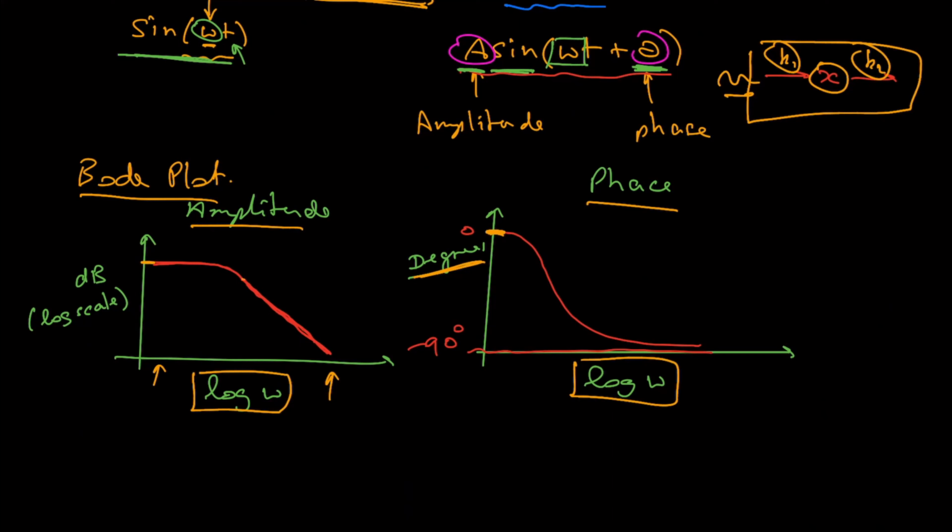So at high frequencies, the system simply cannot keep up with the higher frequency. The phase starts to lag, because it takes time for X to rise and fall, and then you see the amplitude drop. What's interesting is that it drops to an asymptote. It doesn't keep on dropping forever. The phase actually stops dropping at minus 90 degrees. The maximum phase shift you get, no matter how high the frequency, is minus 90 degrees.